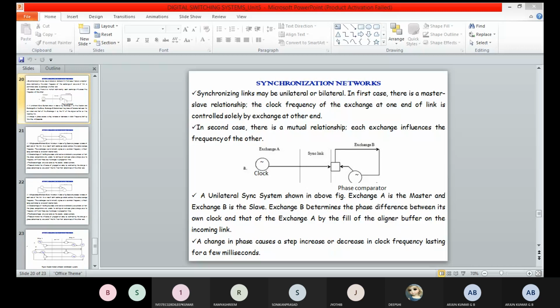To make the connection between these M incoming and M outgoing highways, they will take different time slots. I am taking an example assuming some different time slots. Suppose I am considering time slot X for incoming highways and time slot Y for outgoing highways, then we should choose another time slot, represented by Z, which is free in the connection store of the incoming highway and the speech store of the outgoing highway.